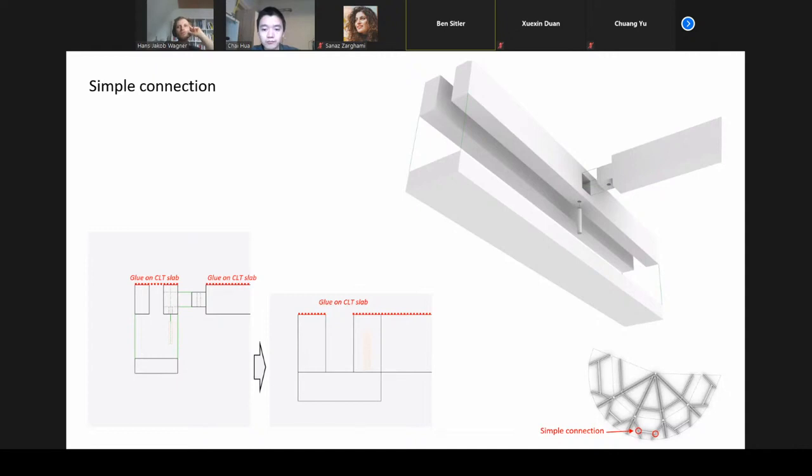I think a lot of current timber tends to be something where you have either 2 layers of beams stacked on top of each other to make something like a continuous two-way grid, or it tends to be something where you've got primaries in one direction and then simply supported beams in the other direction, which are just a little bit less efficient.